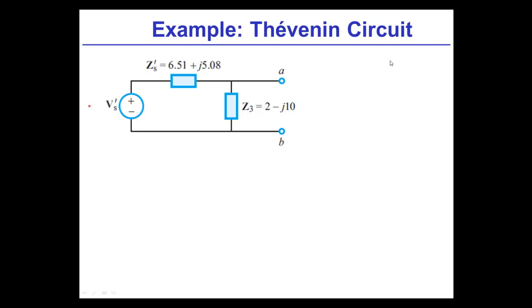So for the Thevenin equivalent voltage, what I can do is just look into the circuit and find the open circuit voltage, right? Following that method, we could look for the open circuit voltage, and that should be the Thevenin voltage. In all cases that's the Thevenin voltage, and the fact that this is in phasor domain doesn't change that. I still analyze it the same way. So how would I do that?